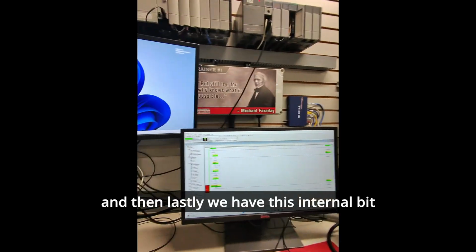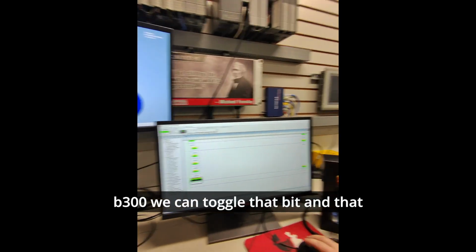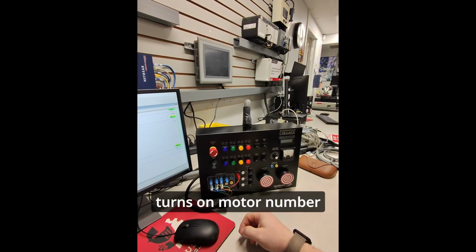And then lastly, we have this internal bit, B3:0. We can toggle that bit and that turns on motor number 2.